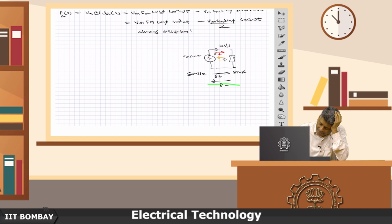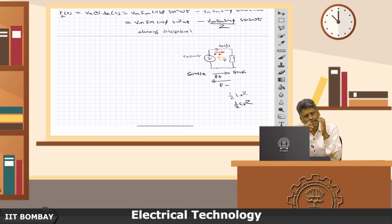But inadvertently, due to the inductive or capacitive nature of the load, this part also happens, because when a current goes into an inductor, you know that half of Li square gets stored in it, or if V is the voltage on a capacitor, then the energy stored in it is half of CV square. So, as per these instantaneous values, the stored energy in the inductor or the capacitor will be increasing or decreasing, but a resistor element